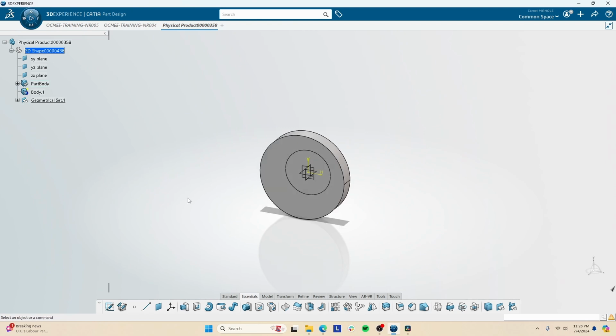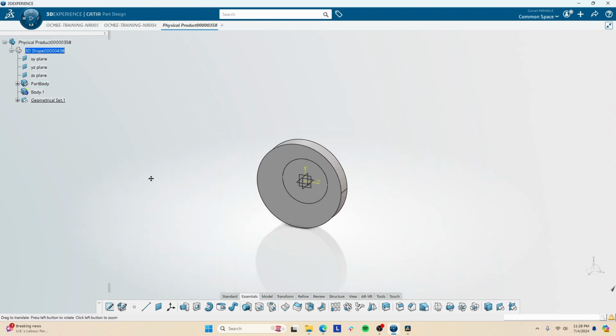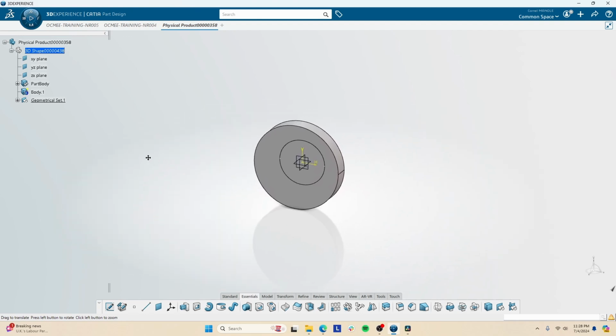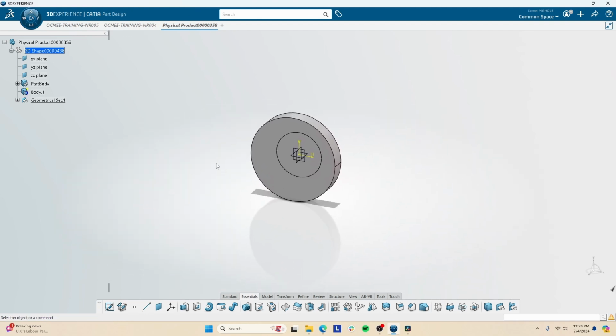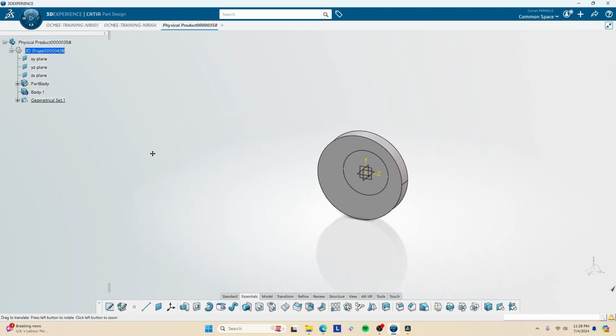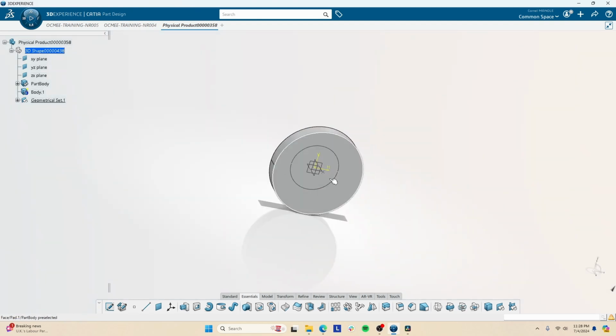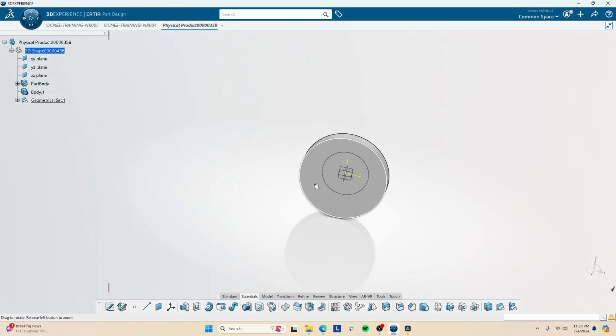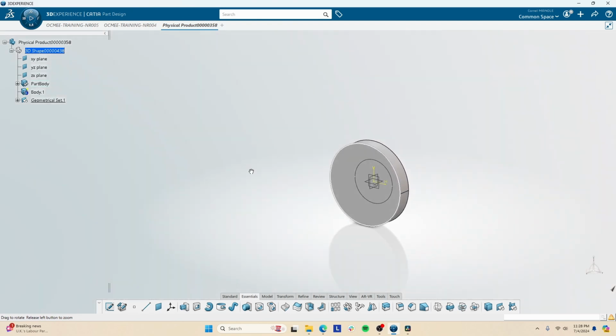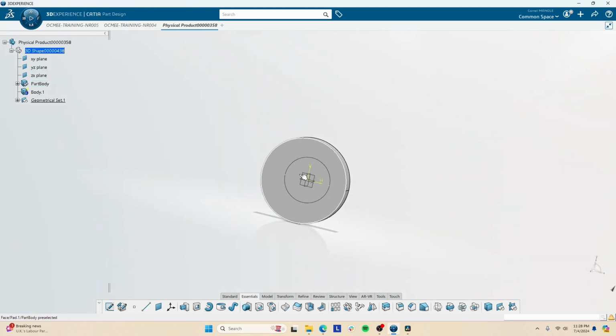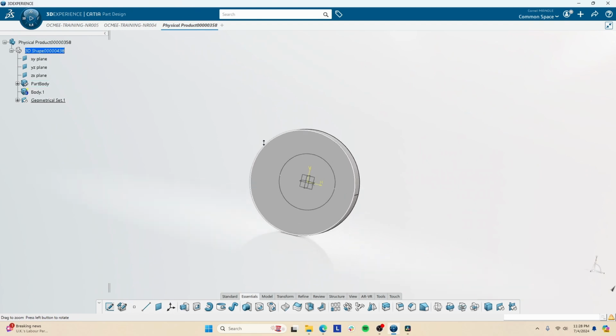Other things that you should know about that I totally forgot about is your navigation. So I'm center clicking my scroll wheel to pan. To rotate, I'm center clicking it again. And then once I hold my center click, I am using either my left click or right click at the same time. So I'm pressing both my scroll wheel and my right or left click to rotate. If I press my scroll wheel and hold it, and I only click my left or right key once and I let go, then I am zooming in and out.